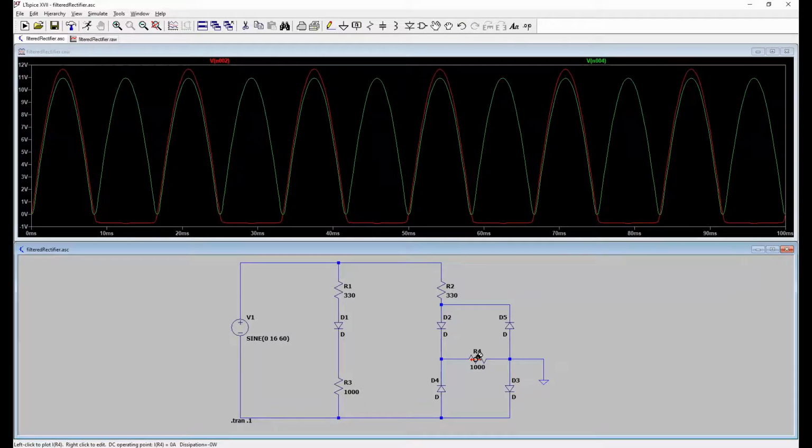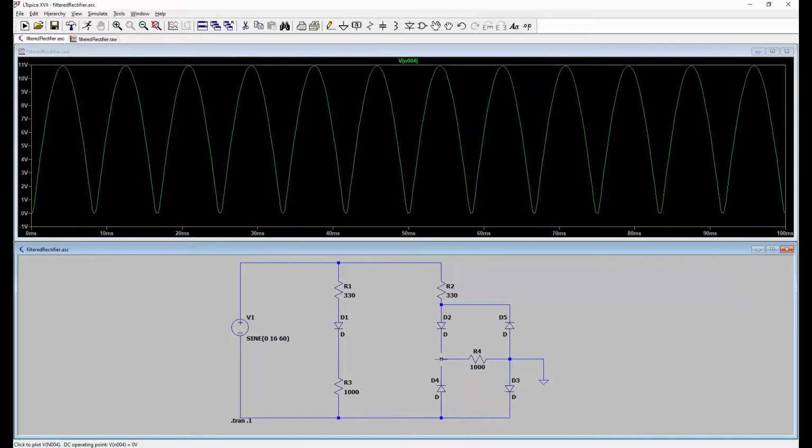So you'll notice that right now, if I was to click on the voltage across R4, it's going to show you a positive, because with respect to this point, it is positive. If I click on the component itself, you'll notice that the arrow is pointing to the left, which is toward the positive, which is wrong.